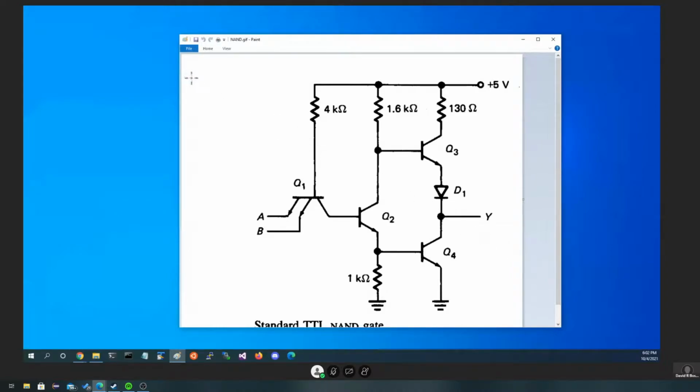We expect for our truth table, we have an A and a B input, a Y output. We'd expect it to be an AND function, which would be 0, 0, 0, 1, except we're the inversion of that, we're a NAND. So we'd expect to find 1, 1, 1, 0 as the truth table for this thing.